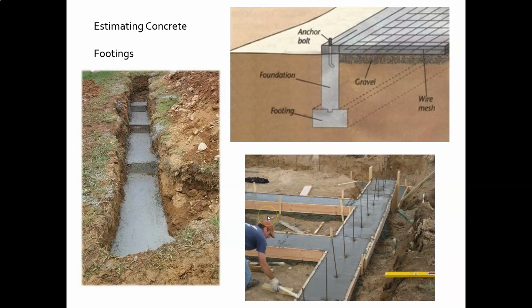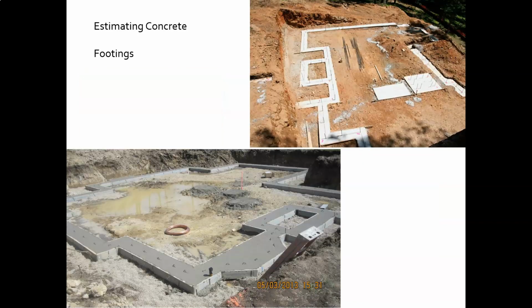Step footings, we pointed that out. So more footings. Here, these look like they might have been poured directly into the earth. If the earth is stiff and solid and stands up, if we could dig a trench and the structural engineer allows it, they'll allow you to not use forms like this. That's what might have happened there, because it looks like the earth is right up to it already.